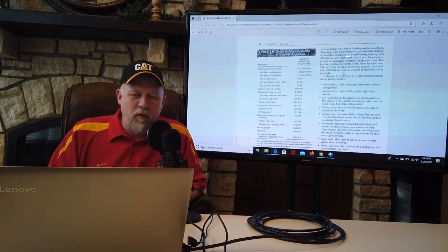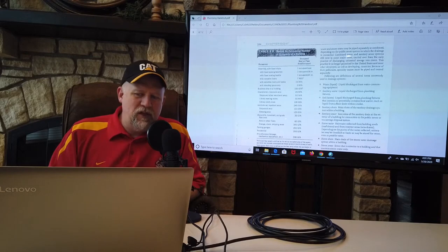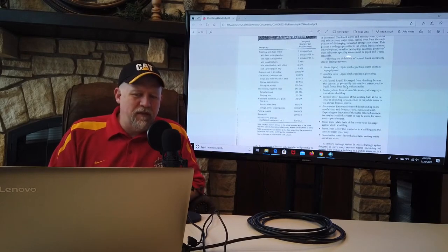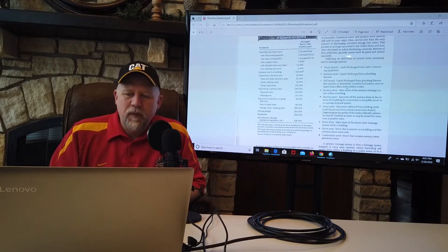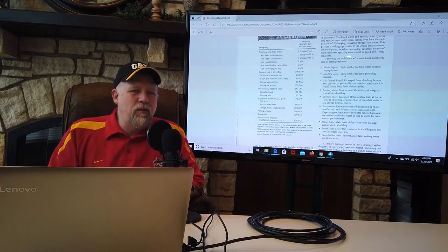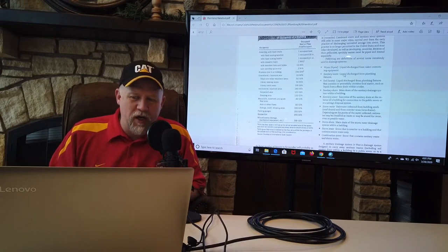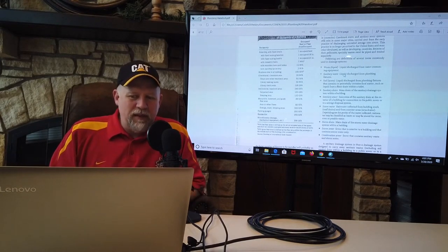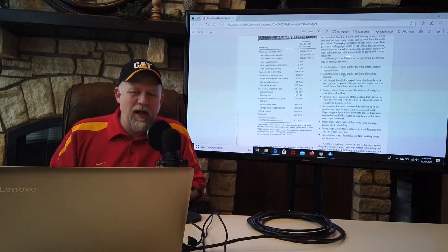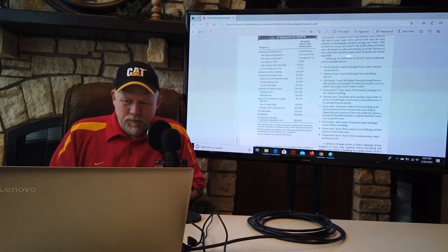Notice there on page 244, we're going to talk about these occupancy numbers in a second, but the following are a definition, all right, some common terms that we're going to need for this class and that you should probably know for industry. All right, waste and sanitary waste are different things. Waste would be like the outlet of a laboratory, somewhere where you wash your hands. It's liquid water, right? Mostly water, maybe a little bit of soap, maybe a little bit of dirt from washing your hands, but it's not sanitary waste. Sanitary waste is discharged from plumbing fixtures like urinals, like water closets. All right.